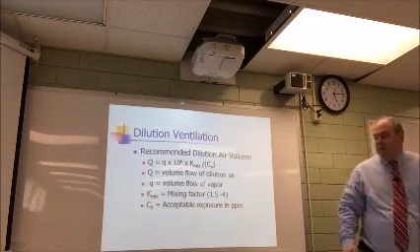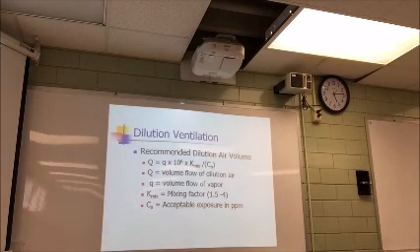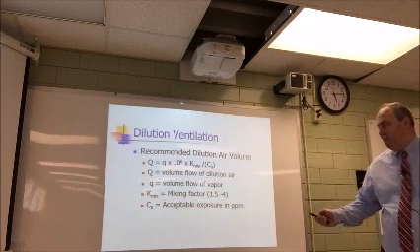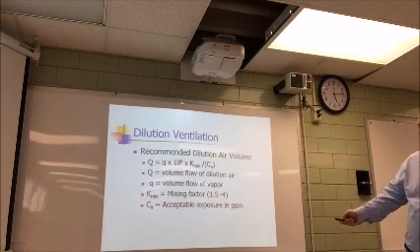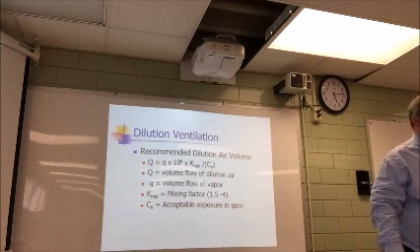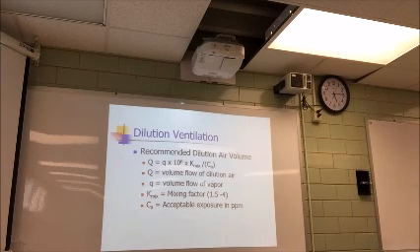Here's also one that you guys will see, and I want you to again look at the formula. This is for dilution volume. Basically, the recommended dilution volume, when you go through that, will be related to this wonderful thing called a mixing factor. If I don't give you a mixing factor, what happens? Yeah, assume 1, assume you don't have to worry about it. And then, what's this CA? What would you guys use for that? Acceptable exposure in ppm. Where would you go for that?